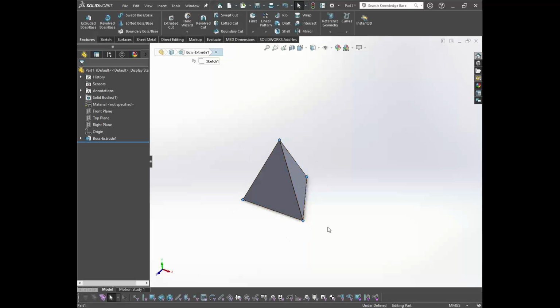And this particular thing is known as an element. So this is the single linear, draft quality element, tetrahedral element, you can call it. There are different elements which we use for different types of geometry. Whenever I want to capture a 3D geometry, like an engine block, which has certain length, certain breadth, and certain height, so all 3 dimensions are significant, at that time I'll go for the 3D or solid elements. So we call them solid elements.